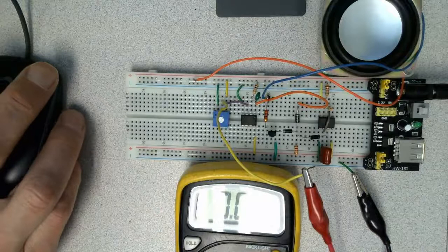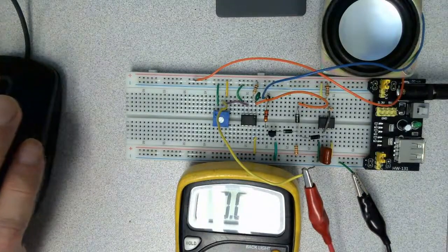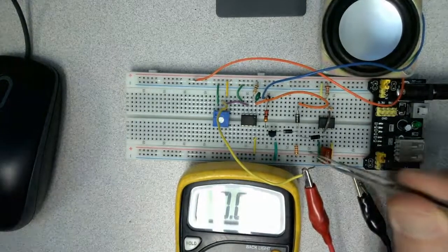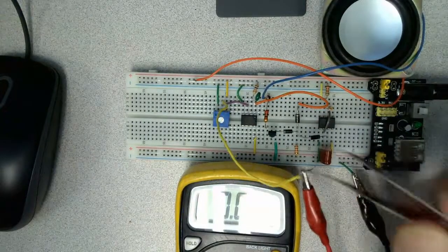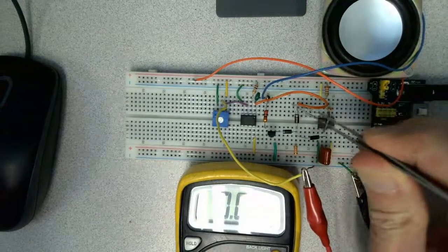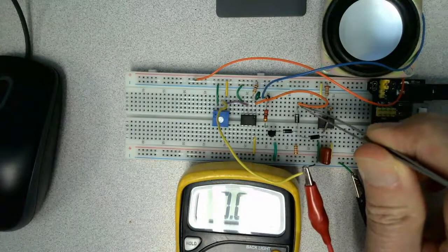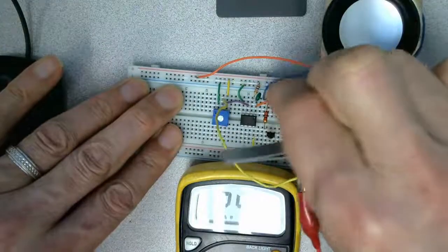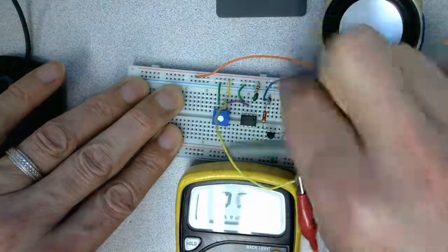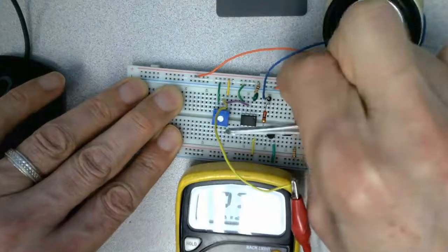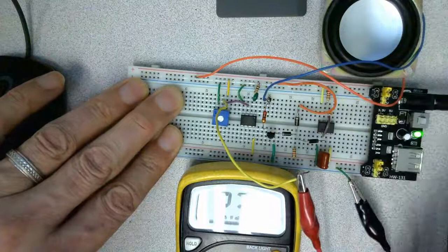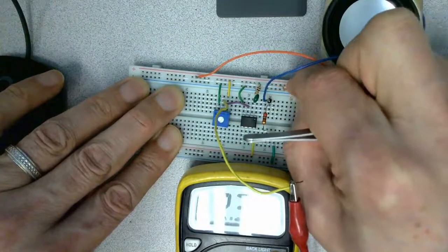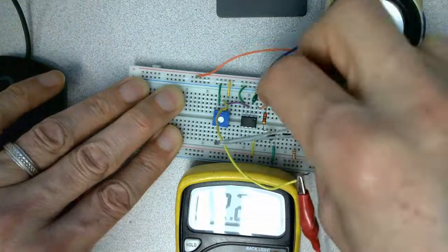So illustrating that, here's my circuit. Find a pencil or something to point with. These are my 3 diodes coming together. Here's the diode that goes to my comparator. If I take that guy and tie it to ground, the speaker turns off. Tie it to 5 volts, speaker turns on, speaker off, speaker on.